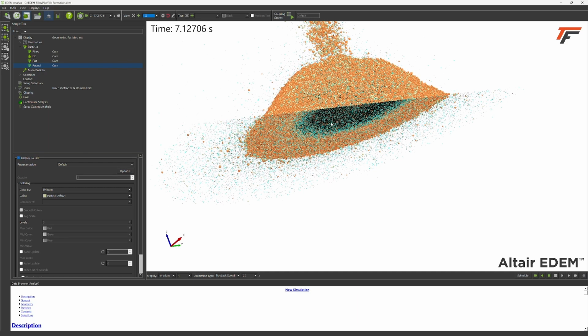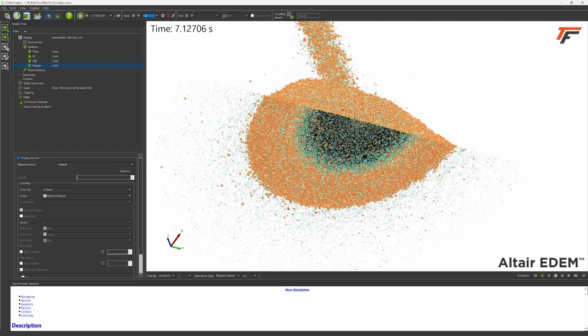The other big thing is your sump. Your center sump is literally right here. This is the true center of the bin right here. So your center sump is right below all this mess of fines and broken corn and the place where you've had no airflow. So right where you need the highest quality grain, the best airflow, when you pull those sumps, you want the best grain to flow into that sump.